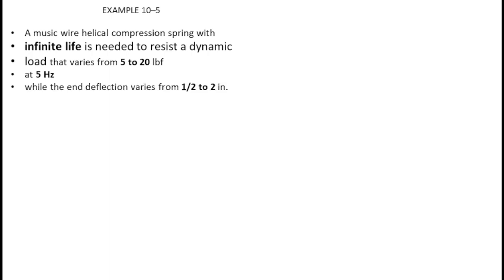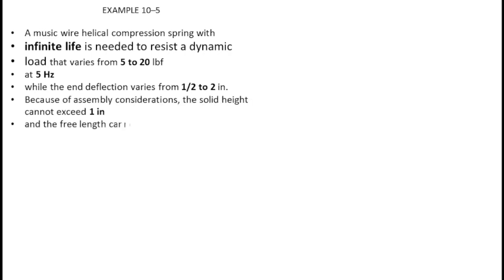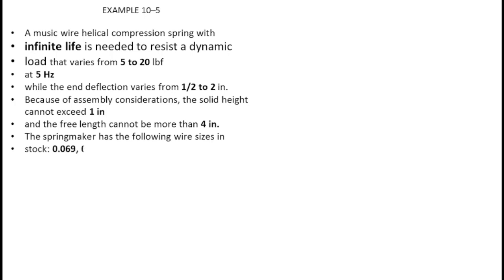And when you apply 5-pound force, the deflection will be 0.5, and as you increase the load, the deflection in the spring will increase such that at 20 lbf force the deflection is 2 inches, and the solid length of the spring should be equal to 1 inch, and the free length should not be more than 4 inches. And you, the spring maker, have only these sizes of the wire diameter.